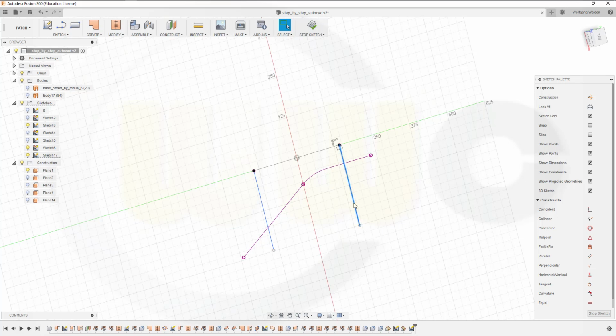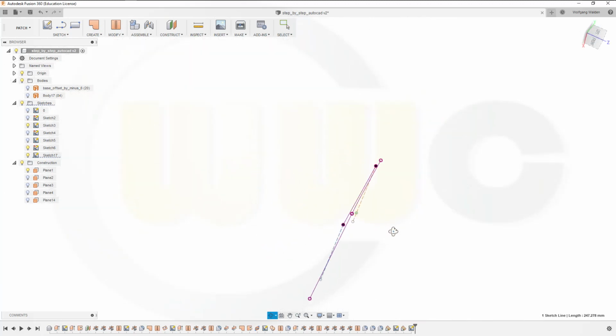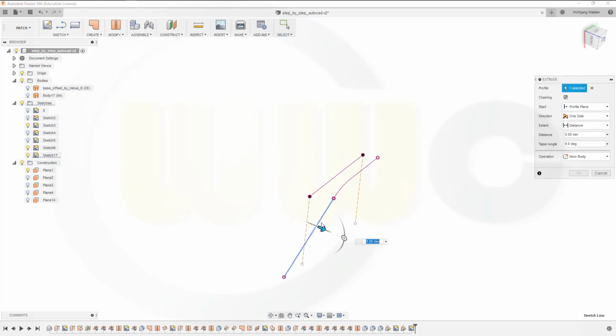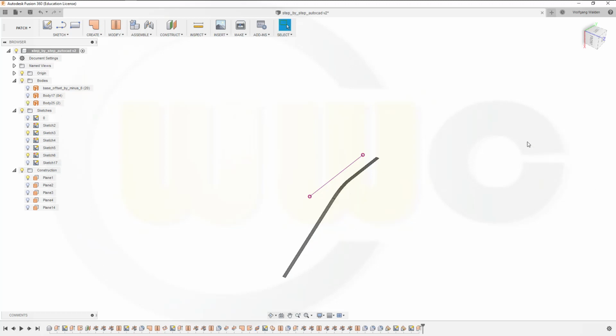So make them for construction only, because I need them for the trim of that surface. So stop that sketch. Now let's make an extrude with that curve right here. So go for extrude with this sketch or curve. And maybe there's a different problem, but let's see. I want it symmetric and total length should be 10.